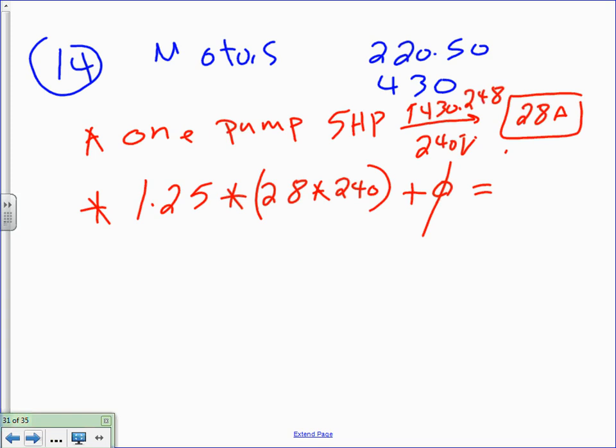Yeah, okay. The reason I had this question asked on my YouTube channel, say, Chad, why do you multiply the volt amps by 1.25? Because we're adding volt amps. You can't add amps to volt amps. It's like adding Chads to Zacks. You can't. That gives 8,400. Divide immediately by 1,000, always by kVA. 8.4 kVA. We always use kVA. So here's the step that you're going to take with you. Don't forget that this also will be divided by what?